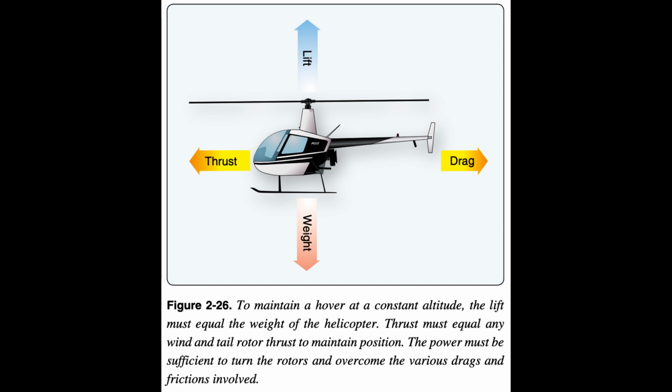To counteract this torque-induced turning tendency, an anti-torque rotor or tail rotor is incorporated into most helicopter designs. A pilot can vary the amount of thrust produced by the tail rotor in relation to the amount of torque produced by the engine. As the engine supplies more power to the main rotor, the tail rotor must produce more thrust to overcome the increased torque effect. This control change is accomplished through the use of anti-torque pedals, see page 3-4.